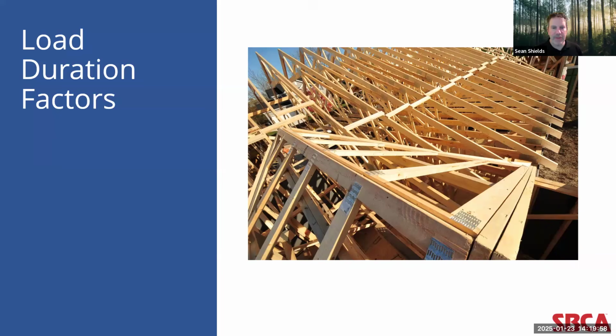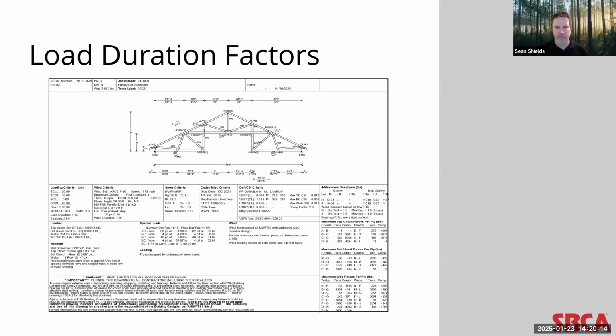This means that the wood can safely resist 60% more than its maximum allowable load as long as that load does not exceed 10 minutes in length. Again, when you think about high wind gusts or seismic activity, that's typically what we're talking about there.